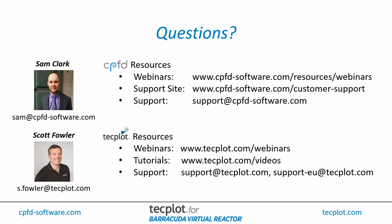I'll just add in here that the way Tecplot 360 works when loading data is we'll scan through all the data just to understand what data needs to be loaded, but we don't actually load the data until it's required. So if you're loading a large transient data set like this, we'll scan through all the data, but then we'll only load the actual data for the first time step. And as you advance to the next, we'll load that data.